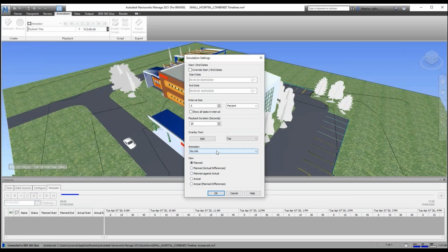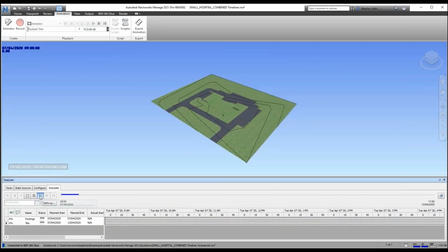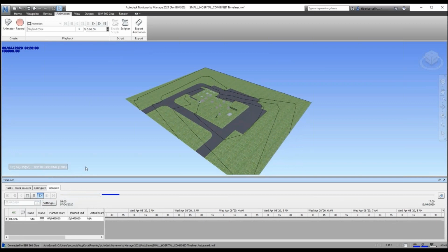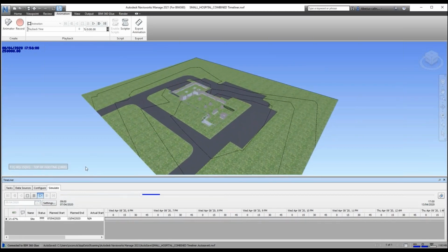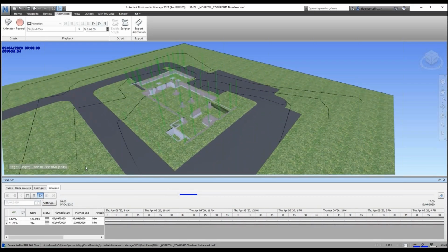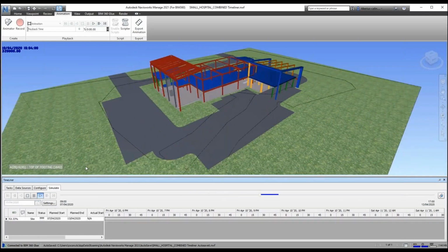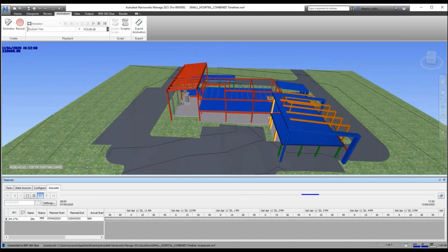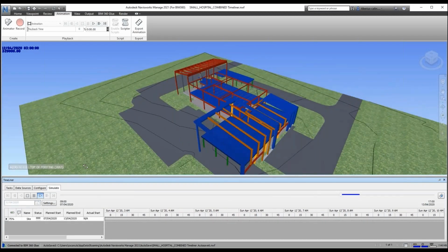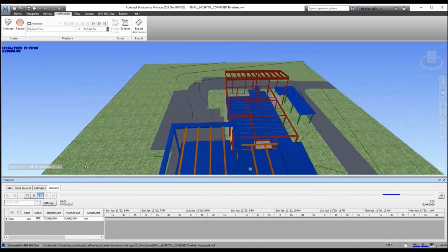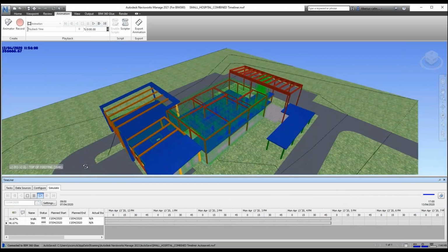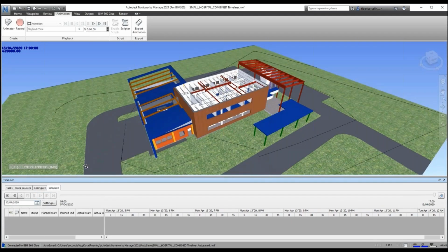Another thing that we can do within the settings is we can add viewpoints animation. Some of you might be familiar with how you make viewpoints animation in Navisworks. It's literally just creating viewpoints, and then the system creates camera rotation and navigation between them. So this is for more angles, better visualization of how things are happening, how things are changing. So this is doing a simulation of creating objects and constructing them while at the same time rotating the camera.